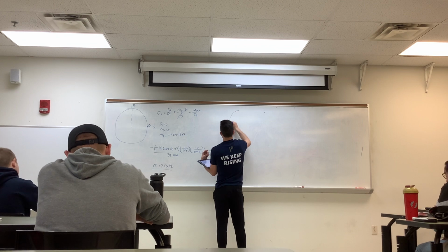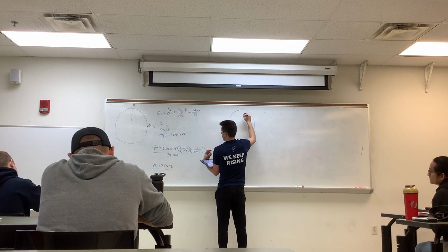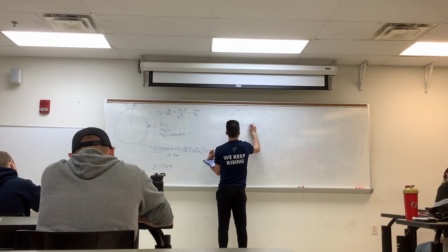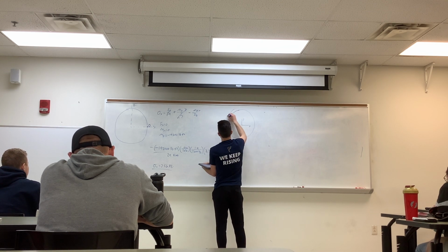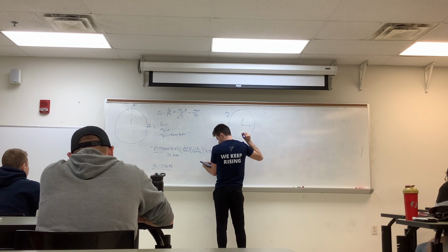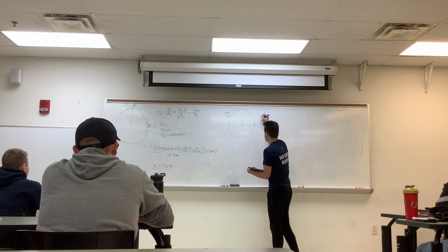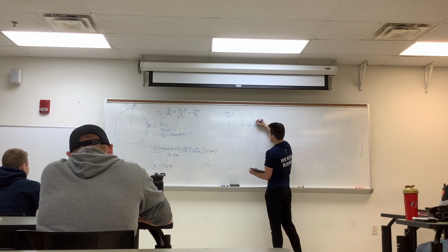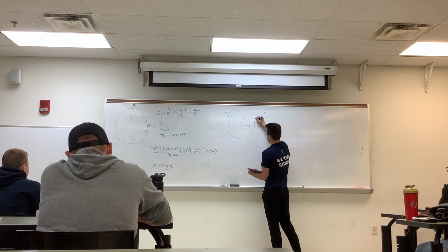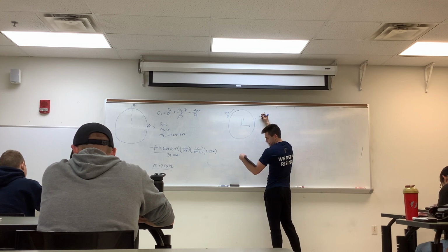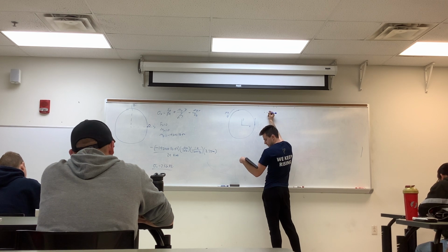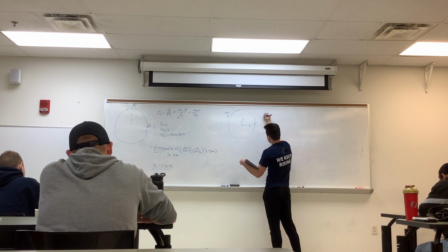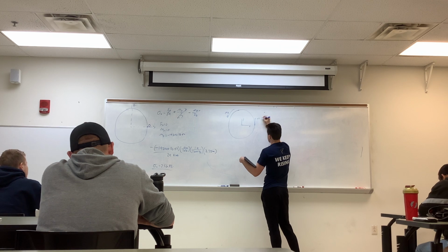So we still have that similar ring. We have our y and z. Then we have our moment about x, or what our torsional moment was. We were looking at point D. The outward normal is positive here. The direction in which the shear is going is perpendicular, so this is along the positive z direction. The outward normal is positive here, giving this one to be positive xz.